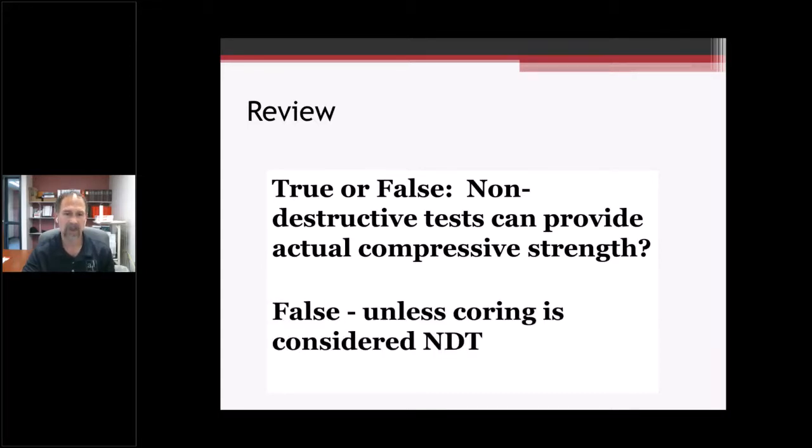True or false, non-destructive tests can provide actual compressive strength. That's false. But if you remember at the beginning of the presentation, I talked about the ASNT definition of non-destructive testing. By their definition, depending on where you take a core, it could be considered non-destructive. But I think for the most part, we all consider coring as a destructive method.